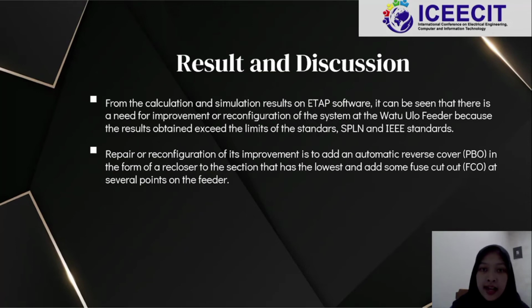And from the calculation and simulation result on ETAP software, it can be seen that there is a need for improvement or reconfiguration of the system at the Watu Ulo feeder, because the results obtained exceed the limits of the PLN standards and IEEE standards.